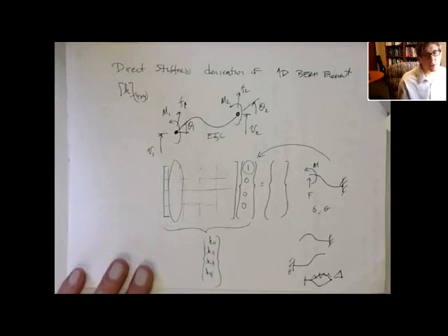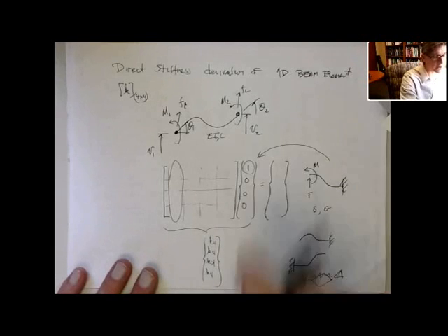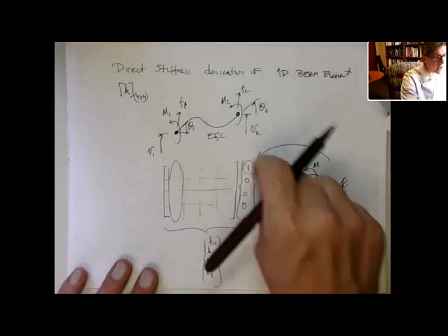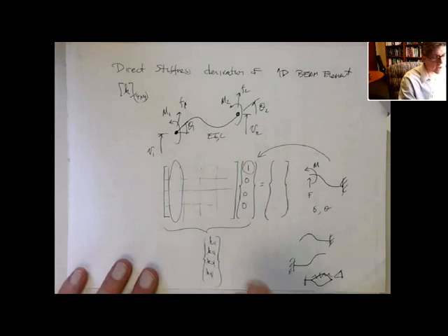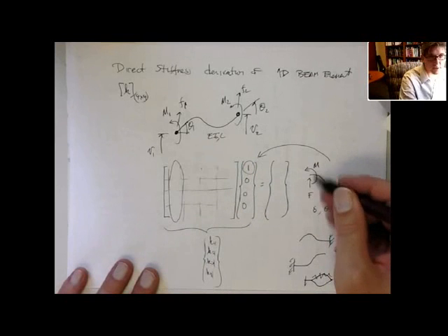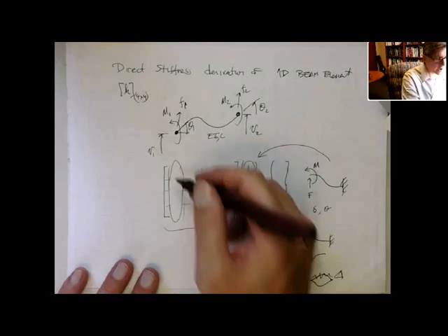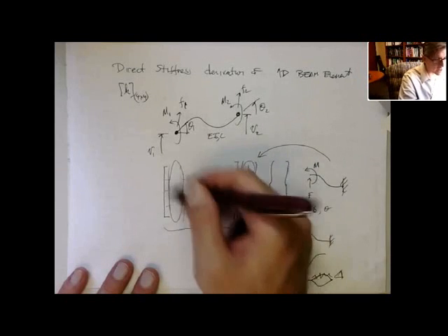So this is similar to what I said. The stiffness matrix is basically like an influence coefficient. So what I'm doing here is I'm saying, okay, keep everything fixed, and I just move the first degree of freedom, which in this case happens to be the displacement at node 1. How does that affect the force? That's what this first column does.